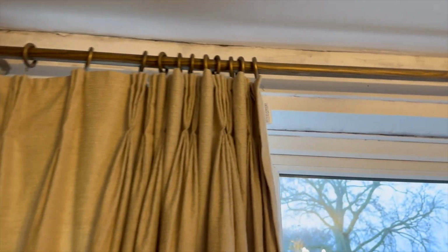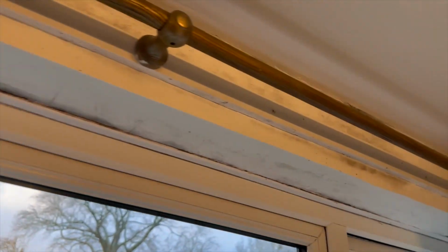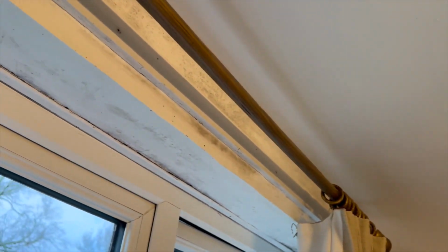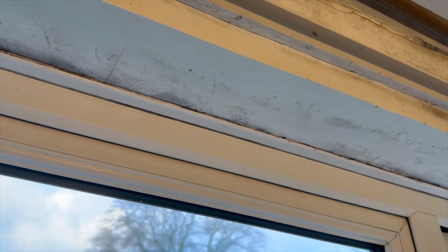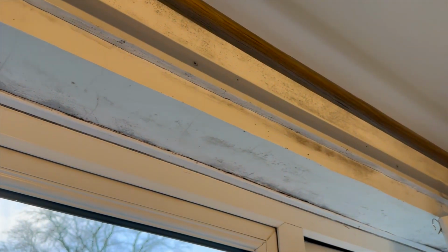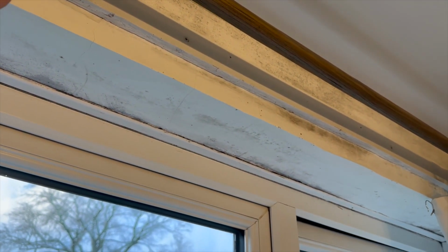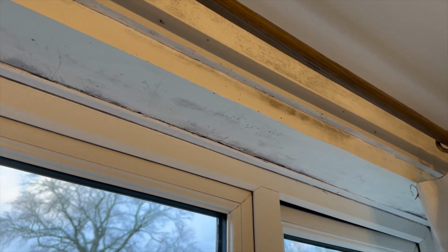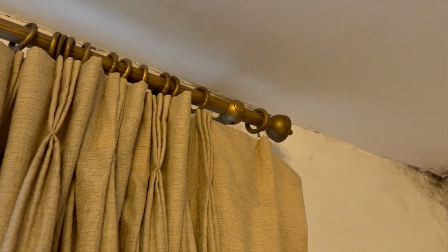There are three things that are influencing this wall here. So you've got the excess vapor, that's the primary cause. The secondary cause is heat loss. So in a lintel like this, you're bound to have metal, and the metal gets cold quickly. You may have some cracks on the outside, and we're going to look at that, but I'm not seeing brown staining, which is the normal sign of penetrating damp.